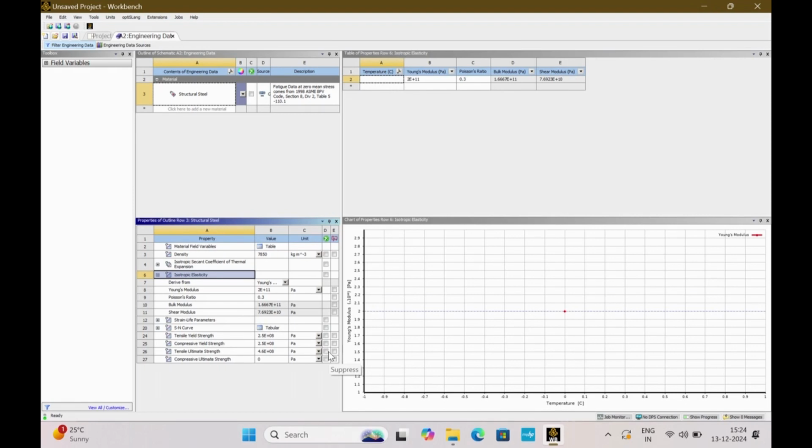Today in the class, Suman sir showed in his presentation that he has taken 500 kilopascal. So that same Young's modulus we will be prescribing over here. In a real physiological scenario, it varies from around 300 kilopascal to around 2800 kilopascal, in that range. Exact range I am not sure, but in that range. So for the time being you just take 500 kilopascal, so 500,000.